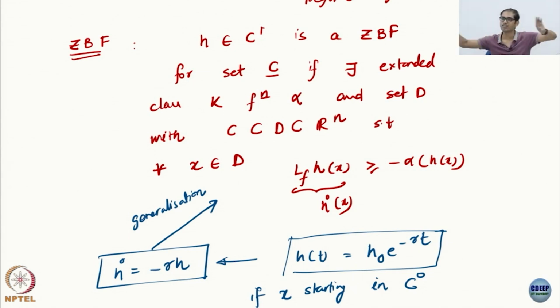The barrier function becomes 0 at the boundary. That is why it is called a zeroing barrier function. On the other hand, when we took the reciprocal ones, at the boundary they explode; here they become 0. So you stop moving at the boundary, therefore we will not typically need a large force to push it back.